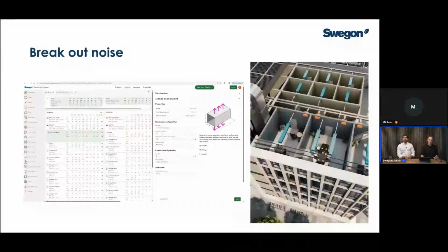So of course you can do this kind of calculation with acoustic design. As well, one other thing that I believe differs from a CAD software is you can cross-check any point in your ductwork to see how much energy from inside to outside the duct you're getting. Also, how much sound will be outside the ductwork. And this is especially sensitive close to an air handling unit. Normally big rectangular ducts are more sensitive to letting out sound. So you can simulate and be very sure what the sound levels will be outside the duct, which can affect the room that is sensitive.